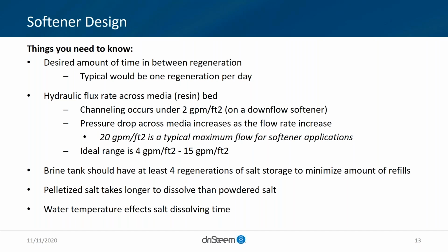The typical thing that, at least at Dry Steam, we try to size our systems for is 1 regeneration per day. Now, there's some places that might have really high hardness and low usage, so you might not want to use a huge tank from a capital perspective. The one thing to note is when you're putting the pelletized salt in, it does take time for it to dissolve. So you need that to occur. Typically, that's about 6 to 8 hours at room temp water.